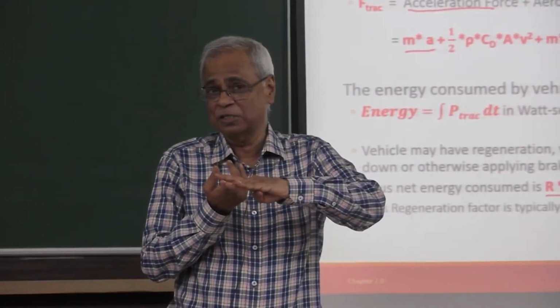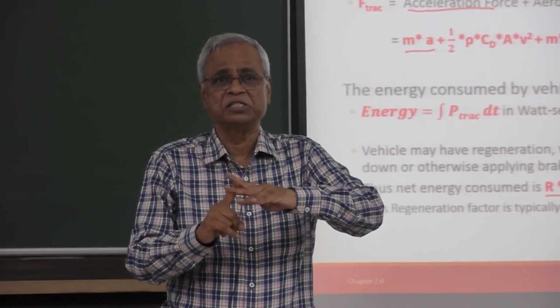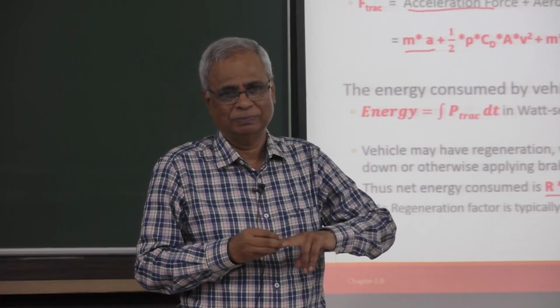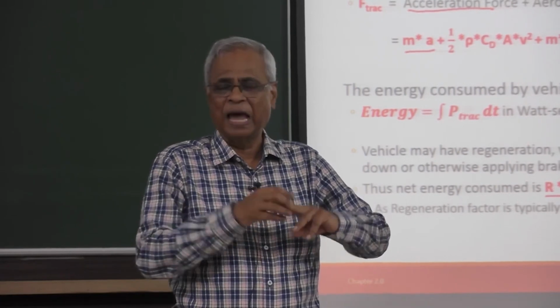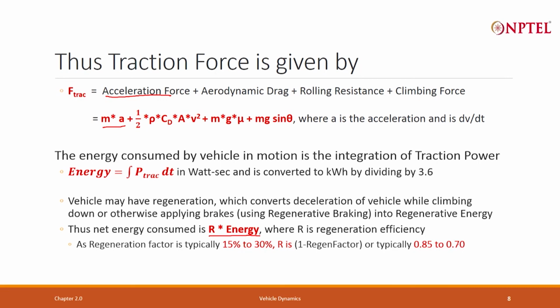what is the energy that you will consume? The aerodynamics and rolling resistance, whatever that energy I will always consume. The climbing and acceleration will disappear. So, this is something that you should keep in mind when we talk about electric vehicles.